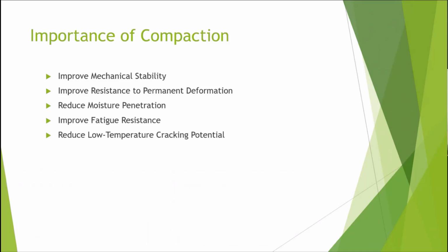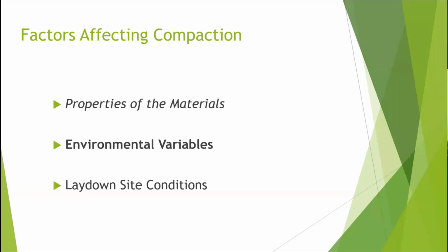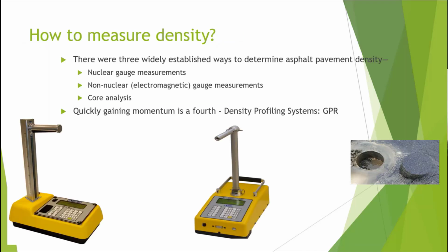The greater the voids, the greater the depth, and I'm not talking like 4 inches into the mat, but another inch of cold, minus 25-degree cold morning temperature at 5 a.m., 6 a.m., getting into that pavement has a lot better chance of inducing that thermal crack, that cold temperature crack. You've probably all seen this if you came through when I was doing paving inspection, but basically there are 3 areas of variables, and the middle one, environmental, is the big one in our part of the world. Time, temperature, location.